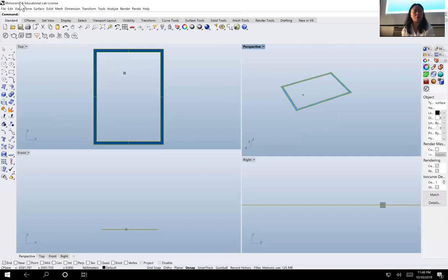When I select the surface, I'm going to this toolbar right here. Sorry, I think it's still this toolbar. The thing is, if I don't remember, most of you would not remember where they are. But click a few times and sometimes something looks quite familiar, and then you will see it. This toolbar is to extrude. What is it called? Extrude straight. Yeah, so this is extrude. If you don't remember the toolbar, you can also type it in. But I'm going to use the toolbar.